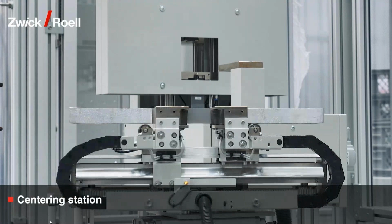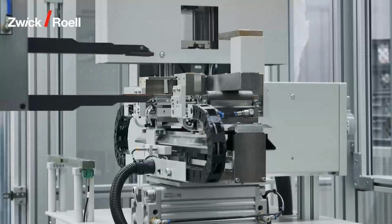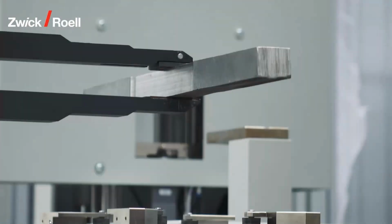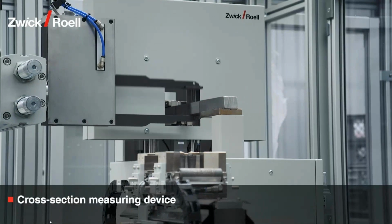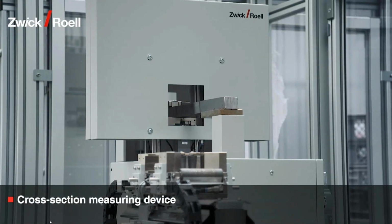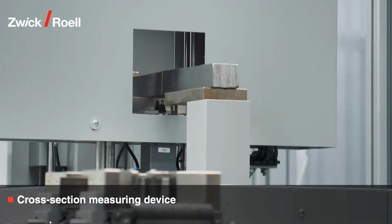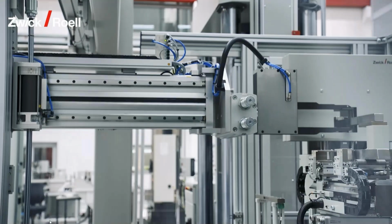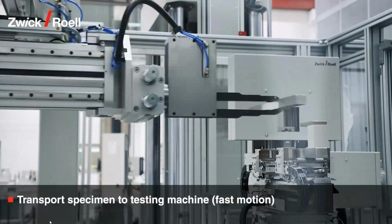Then we are going to do the centering of the sample in the parallel area. In the next step, we are feeding it to the cross-section measurement station. And then we are measuring the cross-section again. That's standard at 3 different positions. In this case, it's really some mechanical transducers. So you saw them attaching. And then we're bringing it to the testing machine.